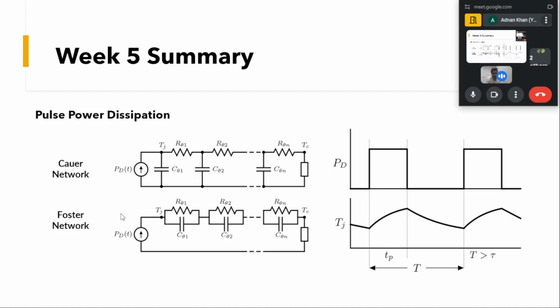And if we know the power losses across these devices, then we should be able to calculate the different temperatures. And also, in case of the design of the heatsink, we should be able to calculate the thermal resistance of the heatsink and choose the proper heatsink for the device, for the converter.